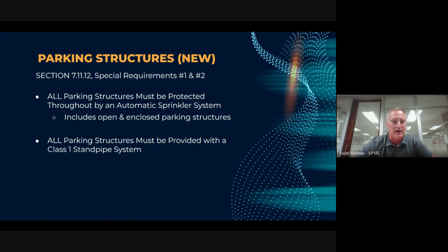A little background to the logic behind the reason why this was added. These requirements are based on recent NFPA, National Fire Protection Research Foundation research on the new hazards with modern vehicles. The design of the vehicles now have more plastics, more combustible materials, in addition to the alternate fuels being used, primarily electric, and the narrower parking spaces within the current designs of parking structures.